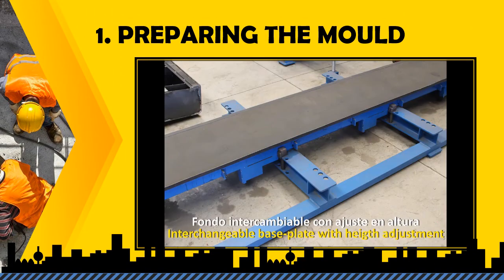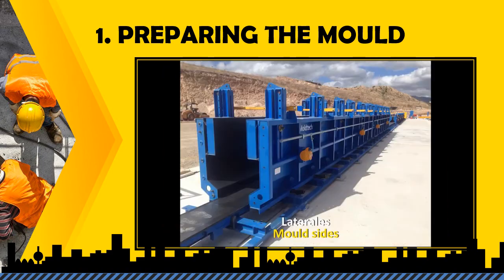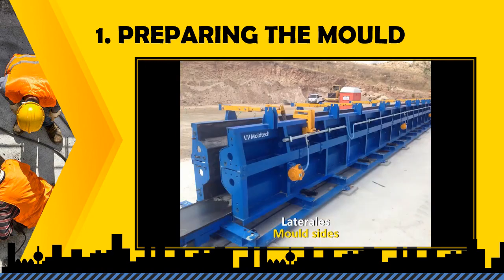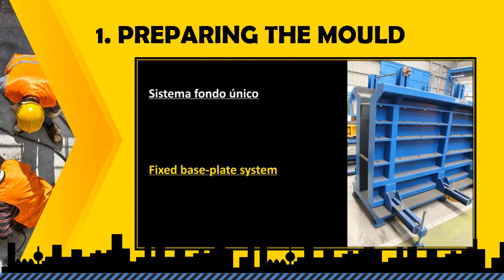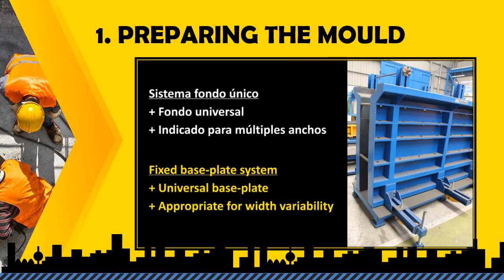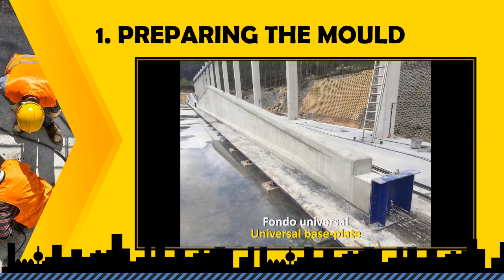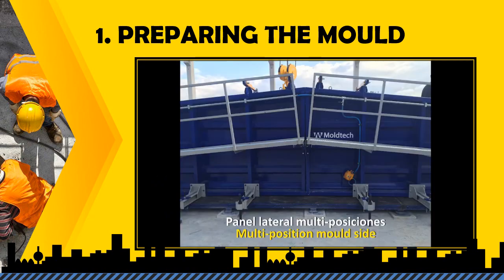The first step is preparing the mold. Before any of the production phases is applied, the mold must first be prepared. For the production of one prestressed beam, the usage of concrete can be plentiful, where the quantity of concrete can be above 4 cubic meters. Therefore, the molds that are used for purposes like this must be very strong, and that is the reason why steel molds are used in the video. This video shows the elements of the mold.